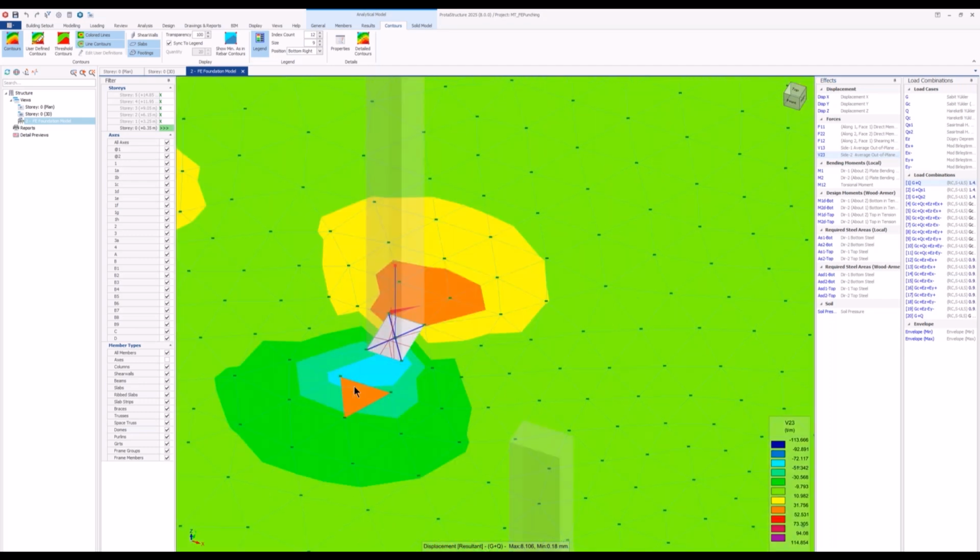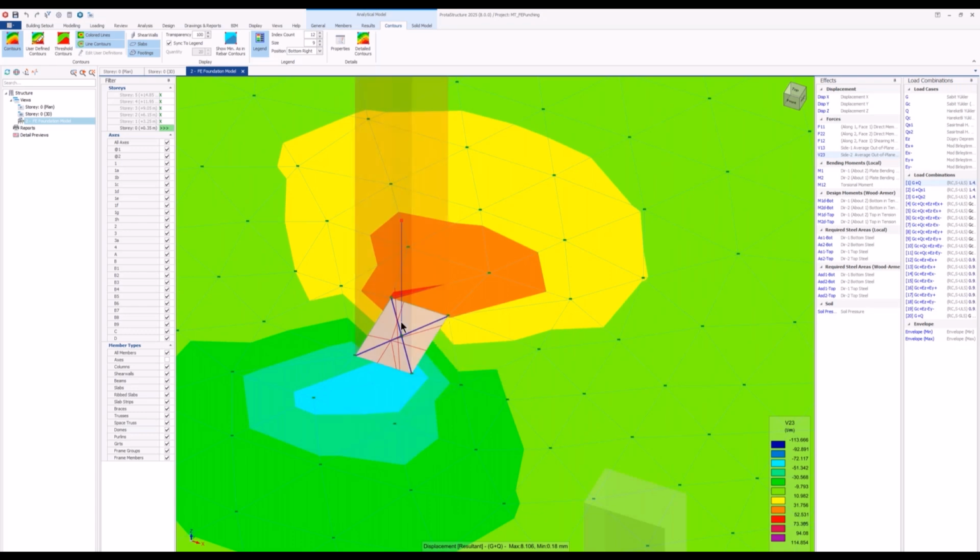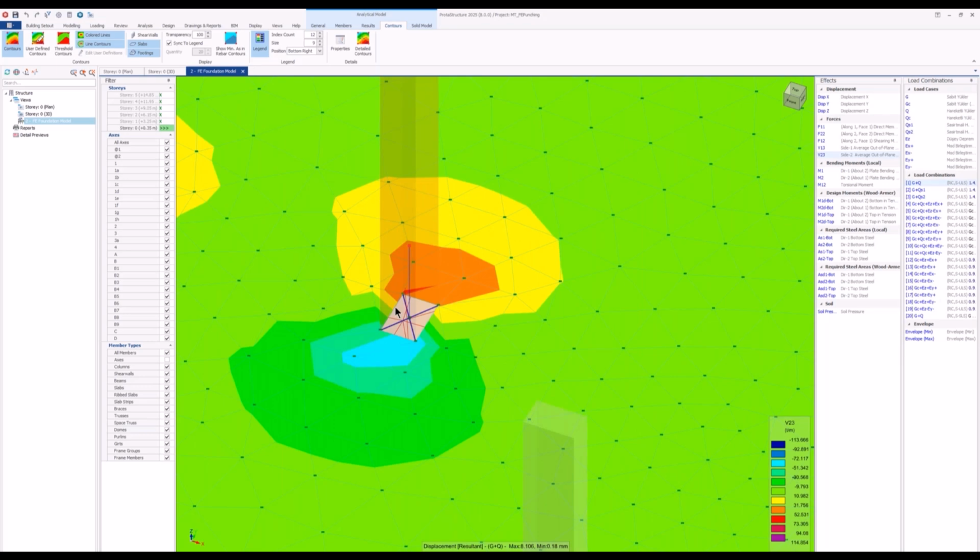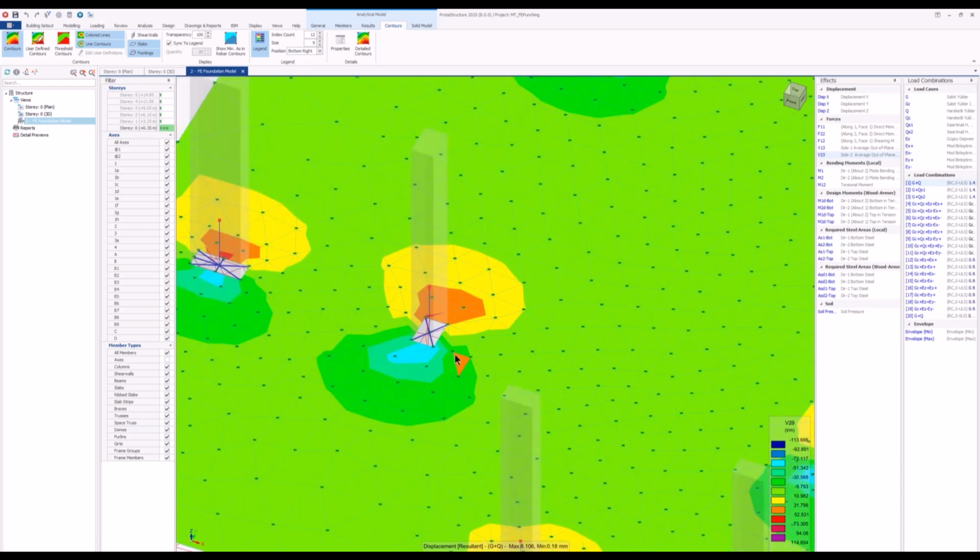First of all, in the latest maintenance update, we will always include the column sections in the finite element mesh. If you have a flat slab or a raft foundation, you will always have these outlines cropped from the mesh, because that will give better results in the punching check. That's what I will come to.